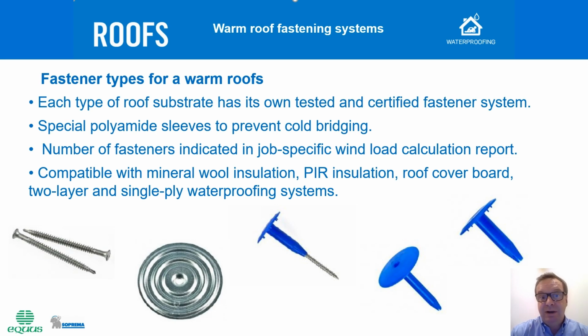Please note that you might need different screws for different types of substrates. In New Zealand, we will use stainless steel screws for plywood, and we have different screws for concrete or for structural steel. The number of screws will depend on the wind load calculation that is done following New Zealand Standard 1170 wind action that will determine the wind load design pressure on the different roof areas. This will then decide how many fixings we place per square meter. I will come back to that later on.